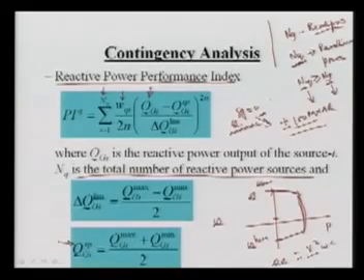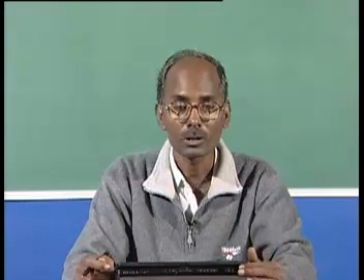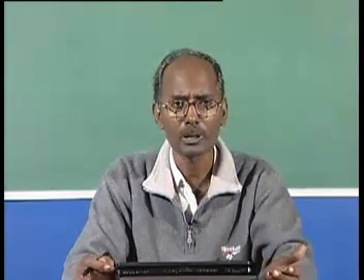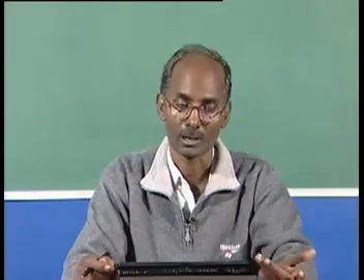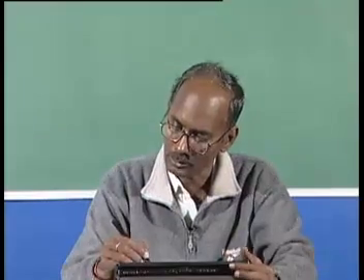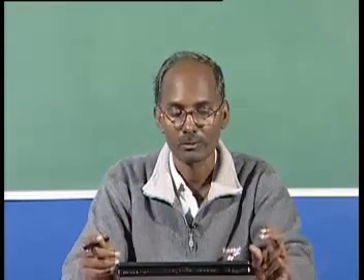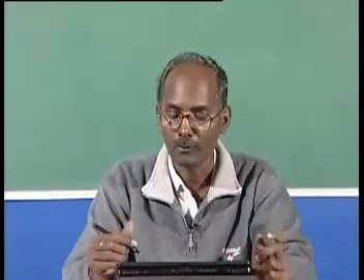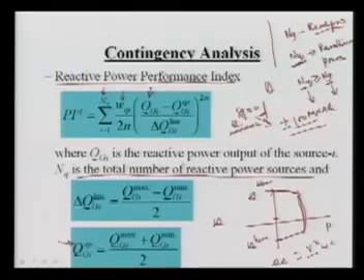For example, we have one SVC in Kanpur, that is a power grid substation. Mostly it is operating in the capacitive mode. It is generating reactive power all the time because our system demands it. But we want that it should generate a very small amount of reactive power or absorb, otherwise we will have less margin. For example, this SVC which we have in our UP, its rating is plus minus 280 MVAR.